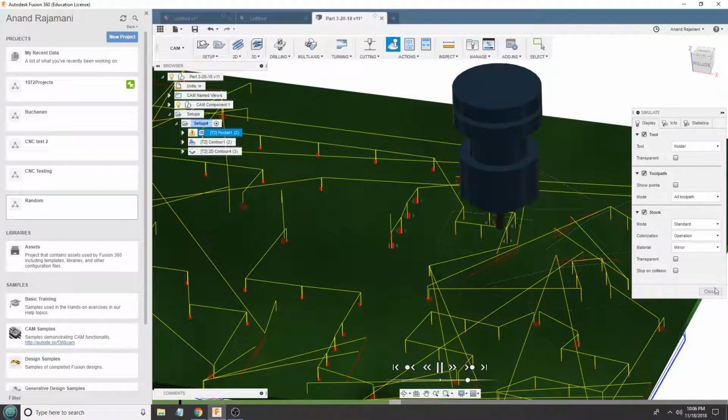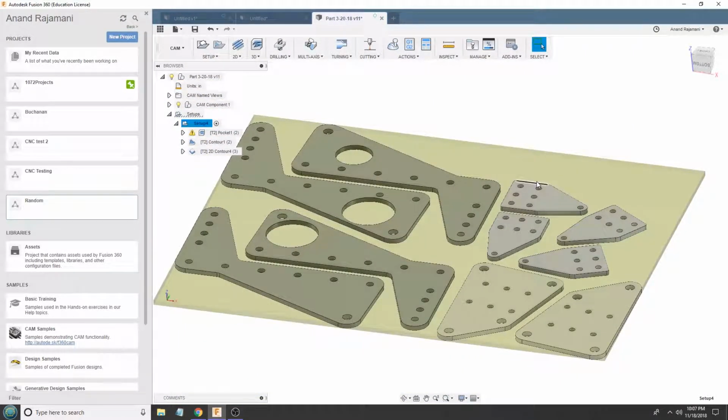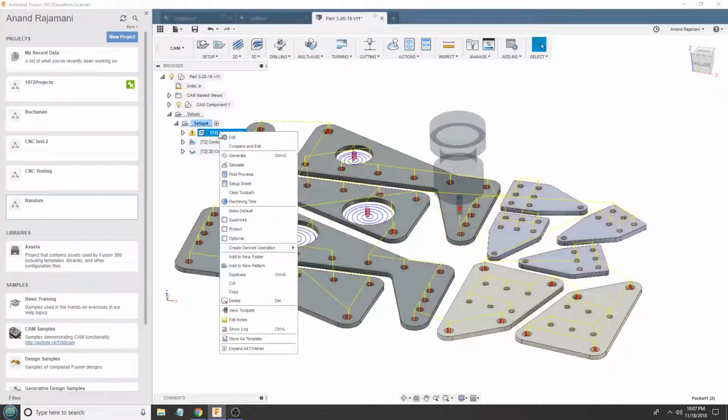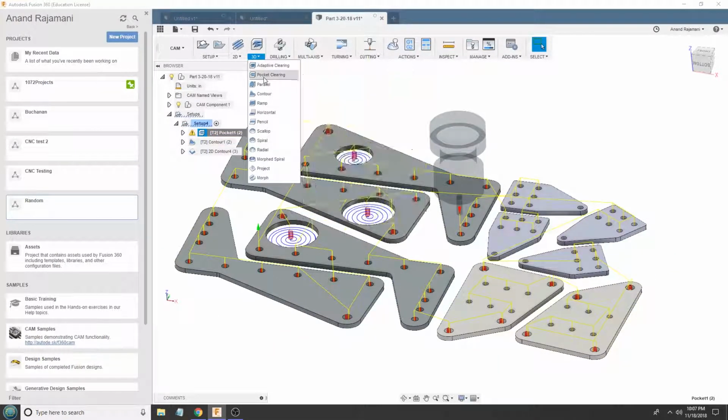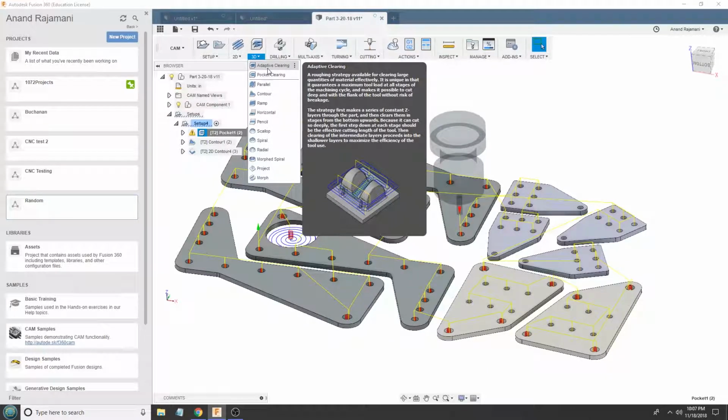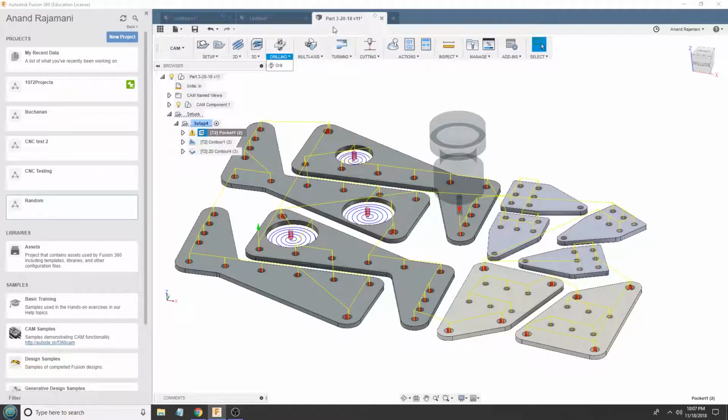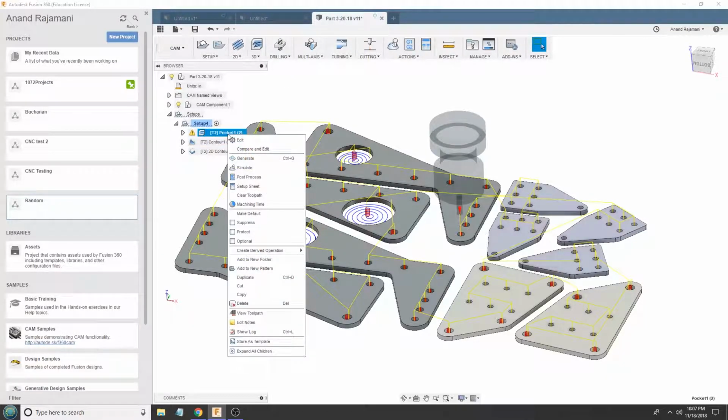So, yeah. Now, you may ask, how do I set up this magic? Well, it's pretty straightforward. So, first of all, you're going to want to use the 3D pocket clearing. You can use adaptive clearing. Don't get me wrong, adaptive clearing is great. It has its place. But in FRC, I used to be a big fan of adaptive clearing because it is kind of like the future, but when it comes to routers, it's not really that relevant.